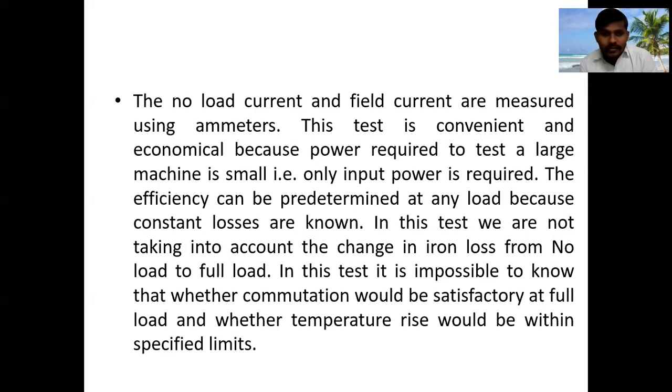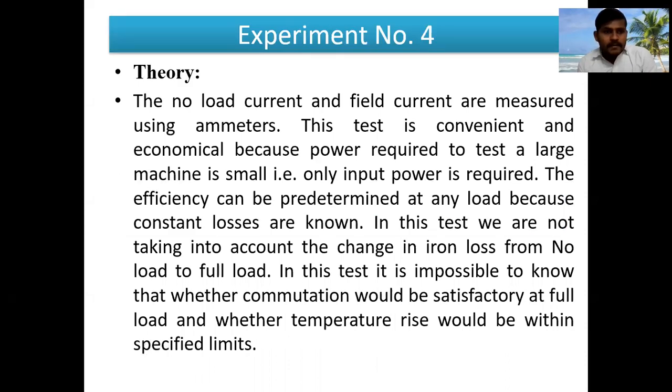Okay, see, the no load current and the field current are measured using an ammeter. And this test is convenient and economical because the power required to test a large machine is small. Suppose we want to perform the test on a large machine.